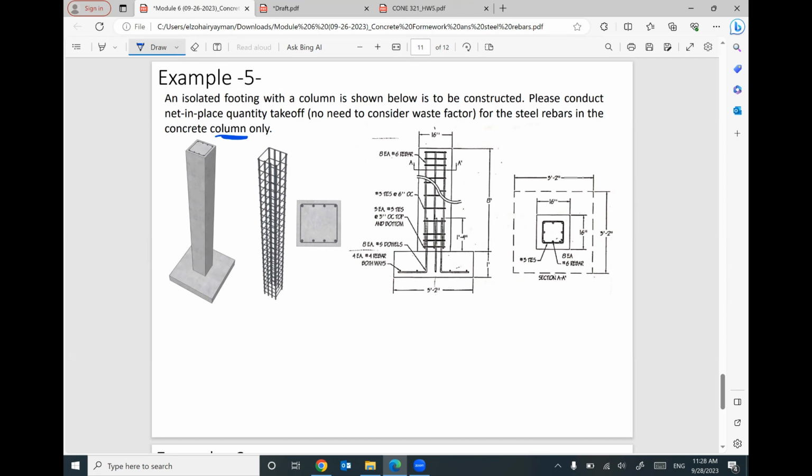So keep in your mind, this shape represents the cross section of your column. In real life, this cross section represents this one. And these points represent the steel reinforcement. We have vertical steel rebar. If you are watching from the top, you will see the steel rebar looks like a point. That makes sense? So if you look at your plan, I can tell you we have number 6 rebar. And we have number 3 ties.